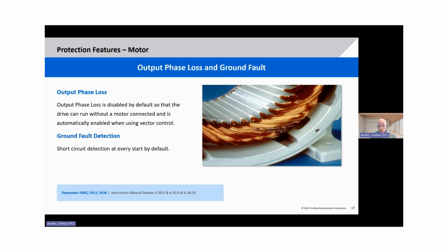In certain applications where you use advanced motor control like vector control or automatic torque boost, the output phase loss function is automatically turned on and you don't have to go and set that.